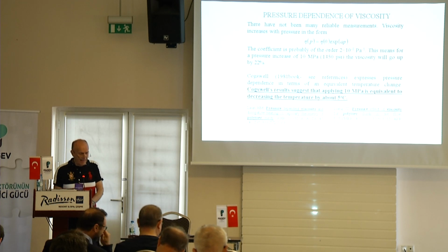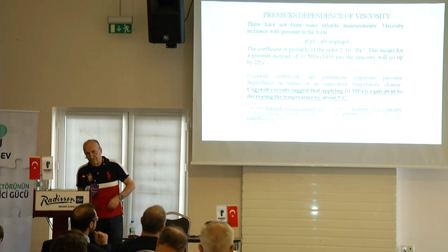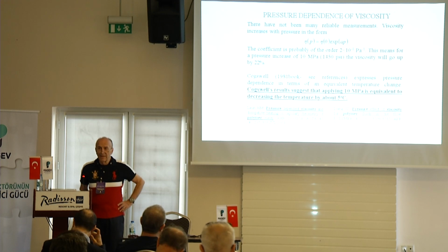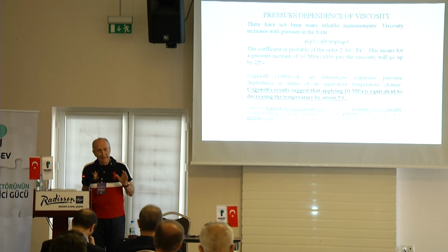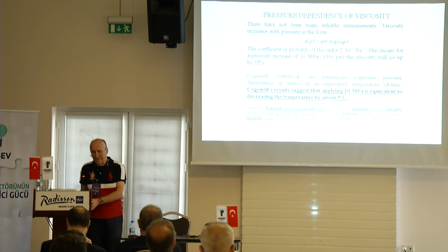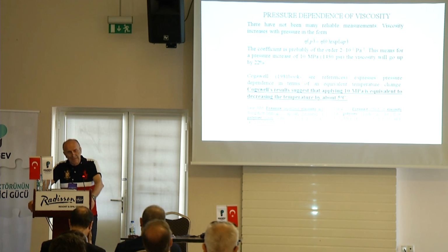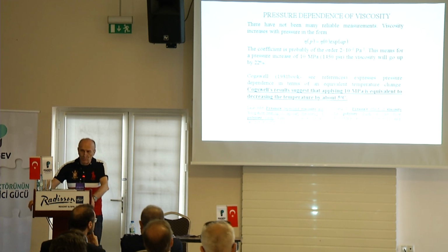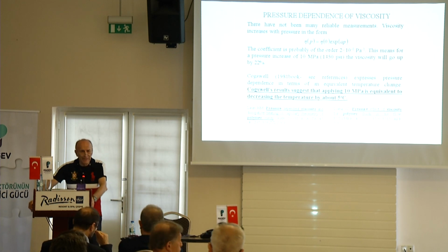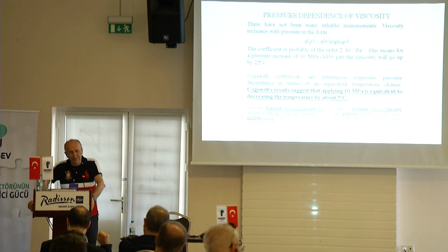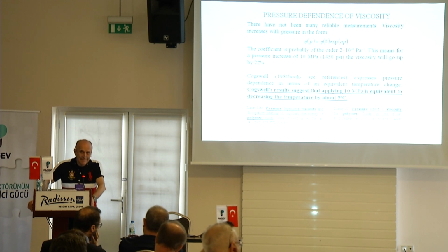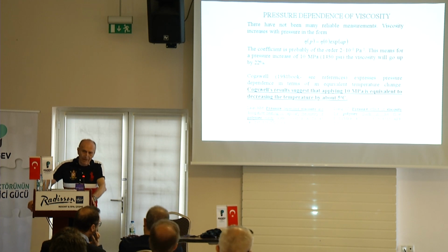Also pressure. Now pressure does have influence on viscosity, and we do not really use it in extrusion, but we do use the effect of pressure on viscosity in injection molding, because in injection molding we are likely to have very, very high pressures, perhaps 200 megapascals, that's 2,000 bar.